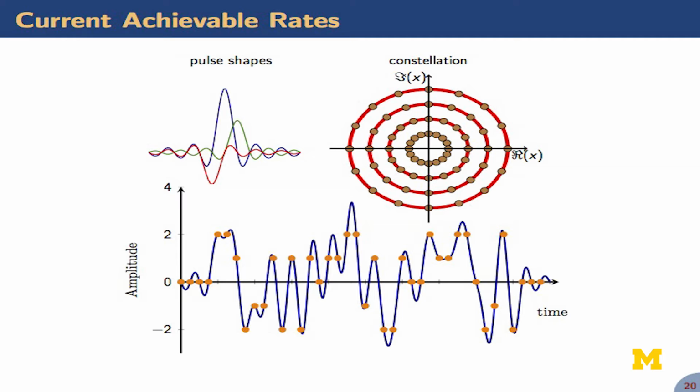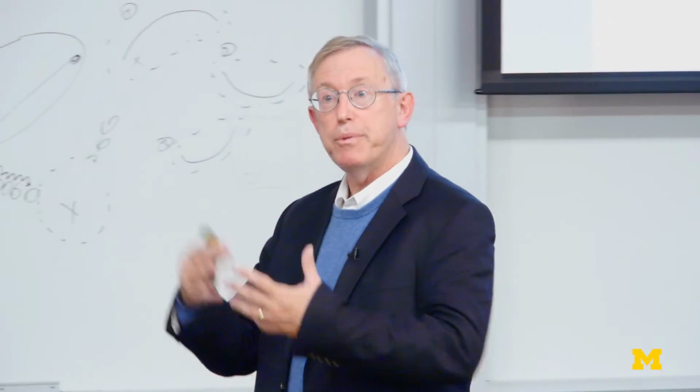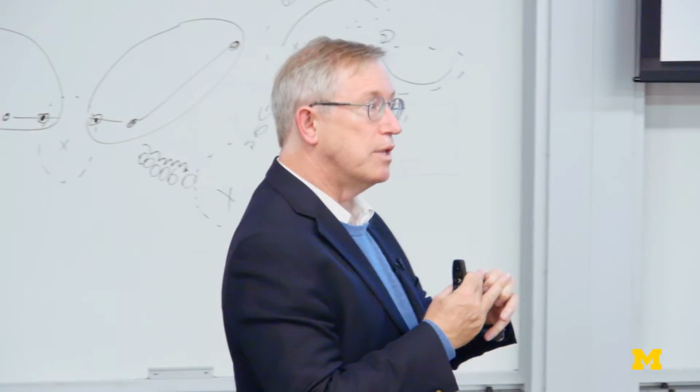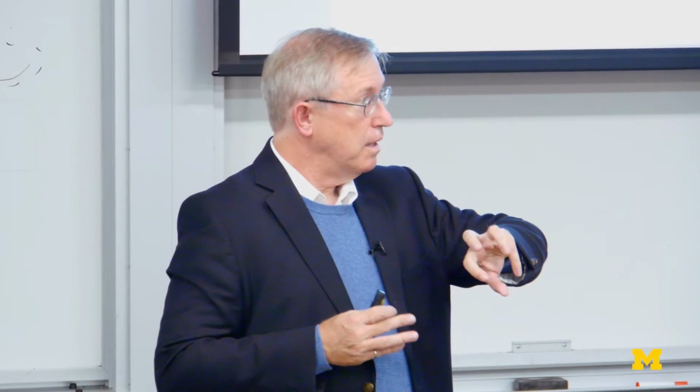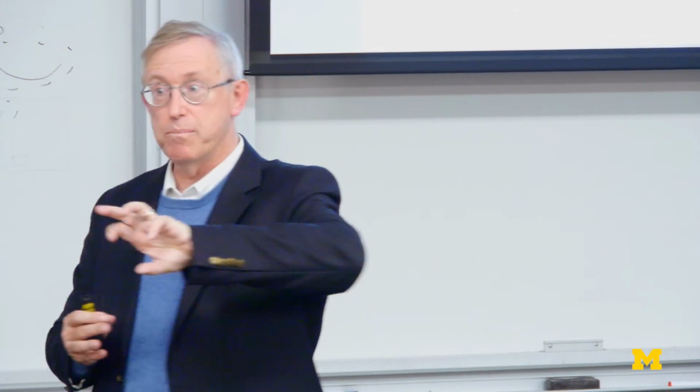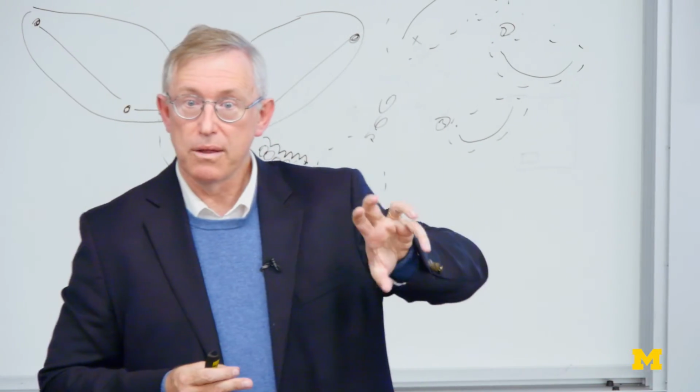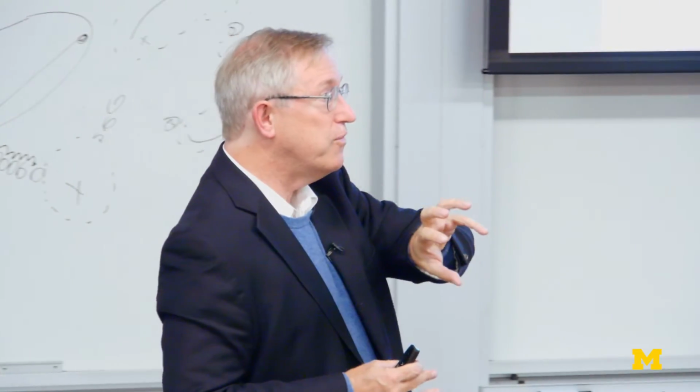Well, one thing you might think about doing is some kind of raised cosine style pulse shapes, some very nice band-limited pulses that satisfy some Nyquist criterion. You might try to excite them with some amplitudes and phases. This channel is perfectly phase symmetrical. It treats all phases the same. So any capacity-achieving input distribution must be uniform in phase. There's no reason to suspect that 0 degrees phase is somehow preferred over 90 degrees phase or anything. So the only uncertainty might be in the amplitudes.